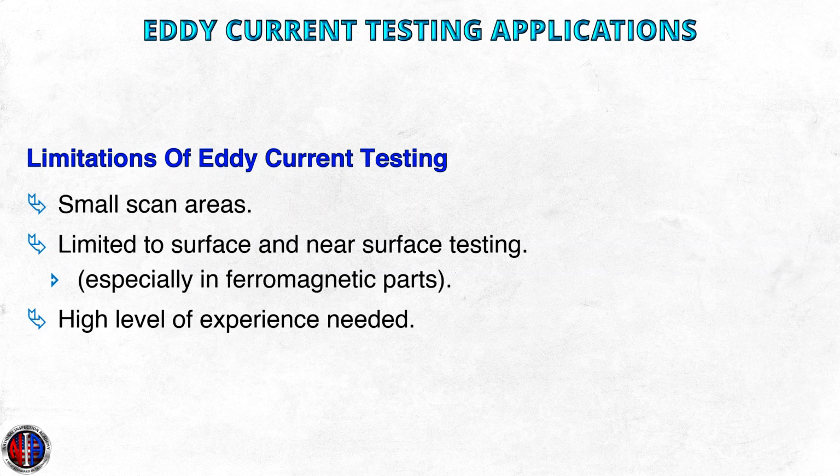Limitations of eddy current testing. The scan areas are very small. They are limited to surface and near-surface testing, especially in ferromagnetic parts. There is a high level of experience needed.